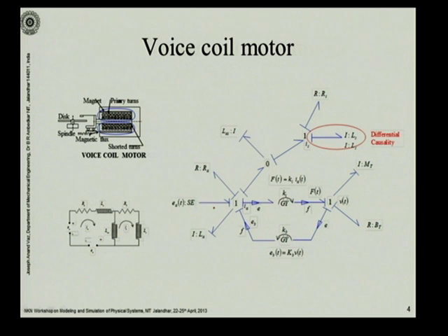There is the electrical side, you are imposing an effort. There is a one junction here. This is the electrical side. This is the armature. This is the current in the armature, or it is the current in this part of your primary circuit. And here you have the inductance, and here you have the resistance corresponding to these two.